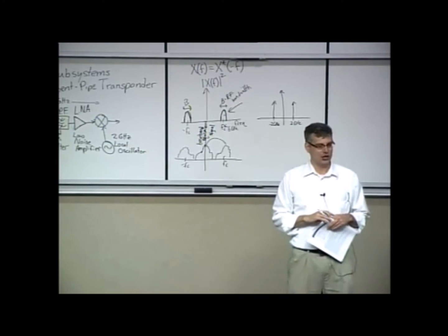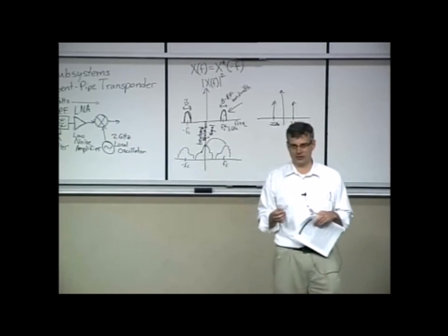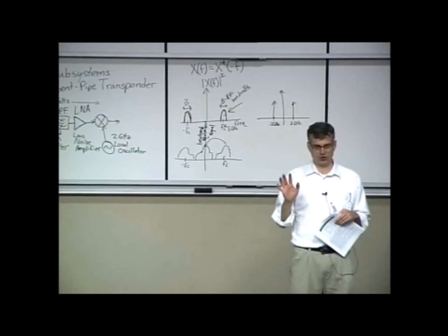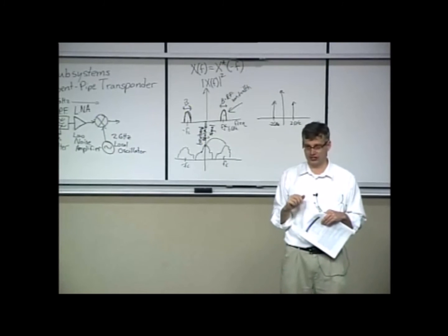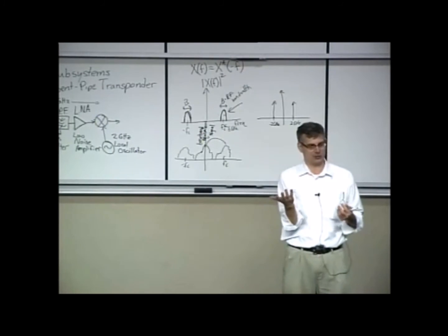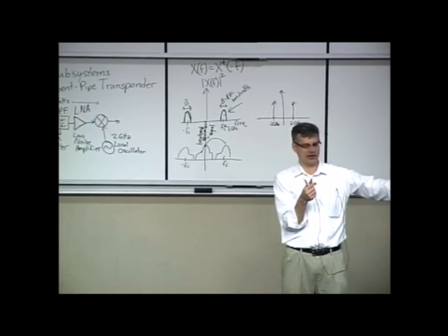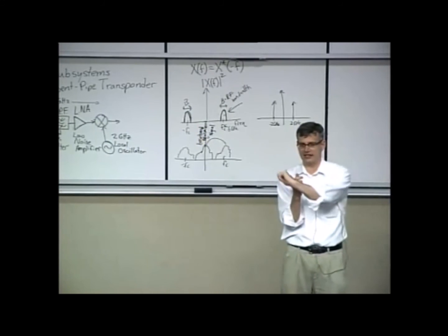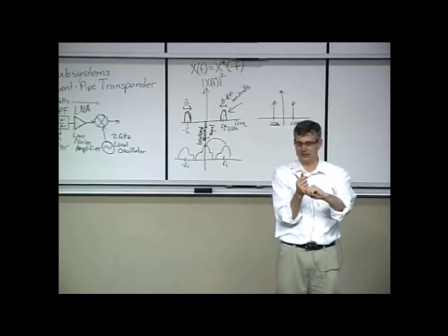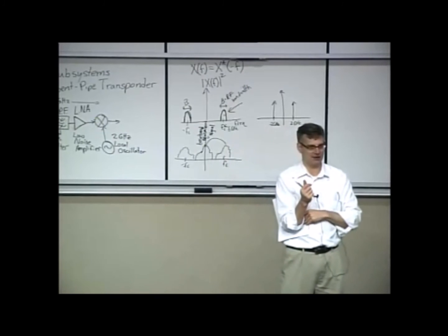Convolution, that's right. When you took your first or second EE class, I don't know where it showed up in your curriculum, the teacher taught you how to do a convolution. It's that folding integral. It's basically how you calculate the output response for a given input if you have the impulse response, right? If you know what the impulse response is, you can take any arbitrary input x, convolve it in the time domain with the impulse response, and voila, out pops the output, and you've pretty much solved the system.